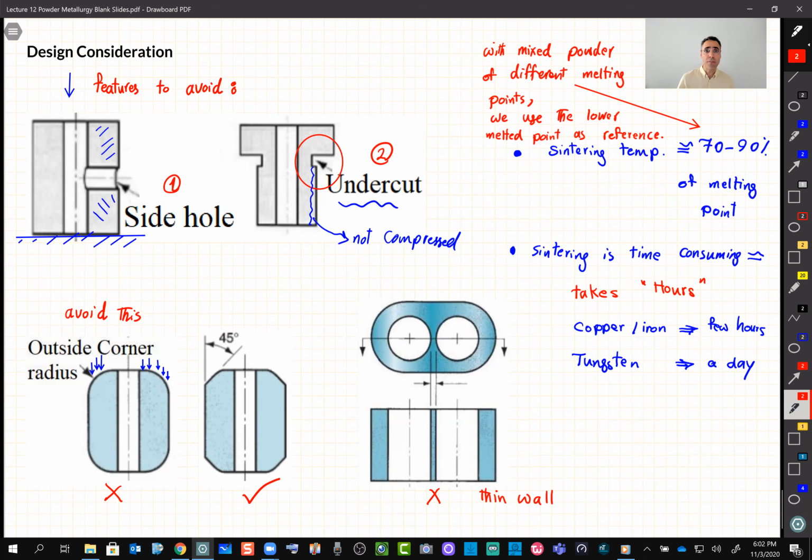If there is a huge difference, an extreme example being a metal like aluminum and plastic powder, then the plastic is going to act as the binder and it's going to melt and fuse things together. So the aluminum is not going to be even touched. But in terms of time, of course, it depends on what material we use. We don't want the higher temperature material to act as a binder. Does that make sense, Ahmad, or no?